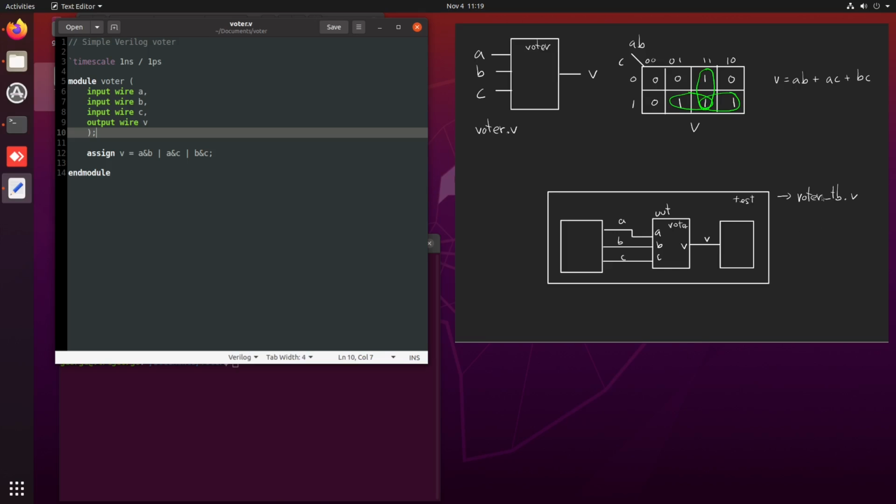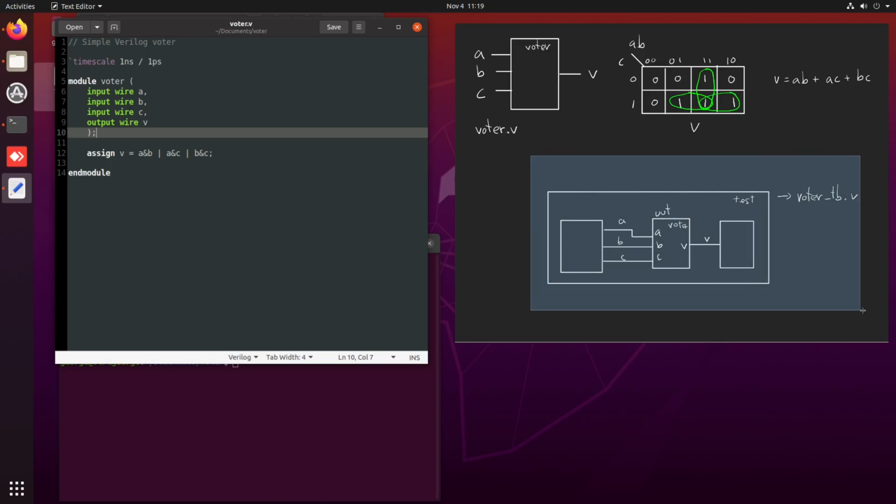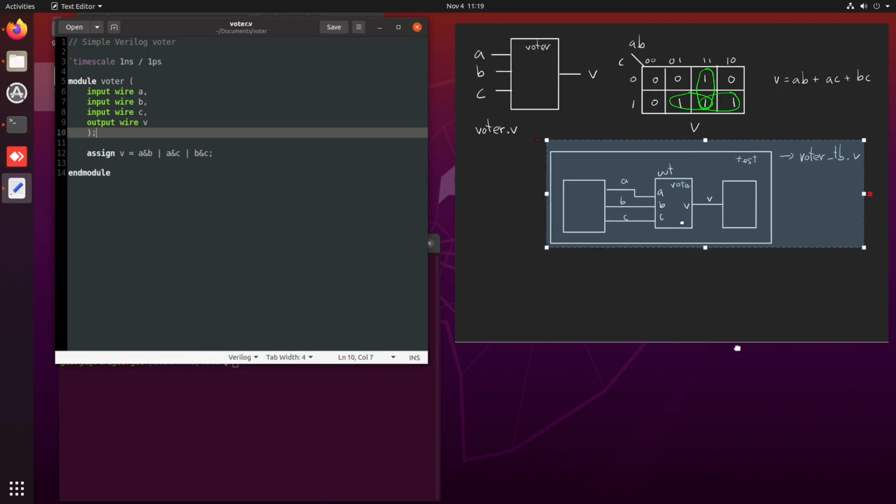For the test bench we will use a different file because the test bench is a part of the Verilog code that I will use only during simulation. After the simulation, I know my circuit is correct, and I can then use my module in another design, and I only need the file defining the code of the module. So this is the overall structure of a test bench.